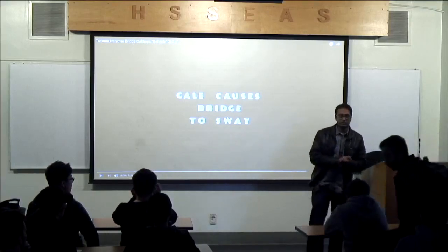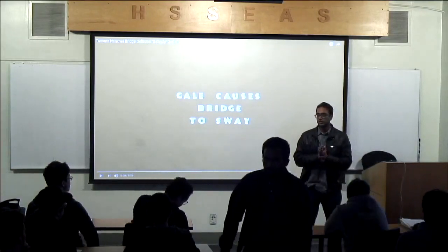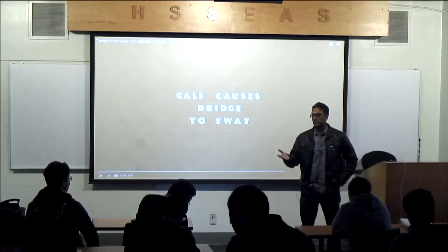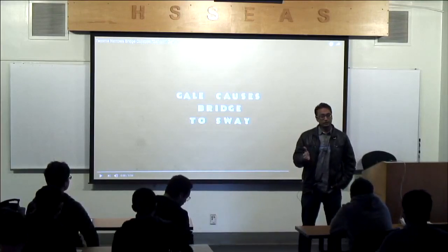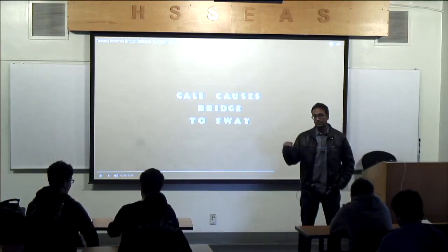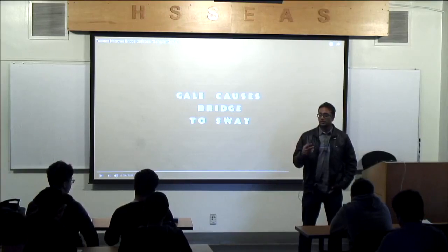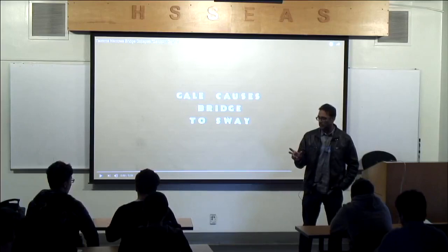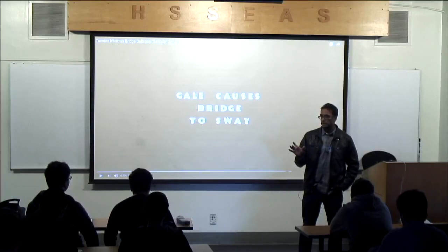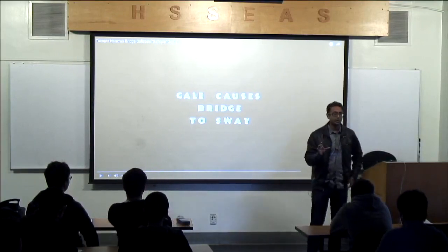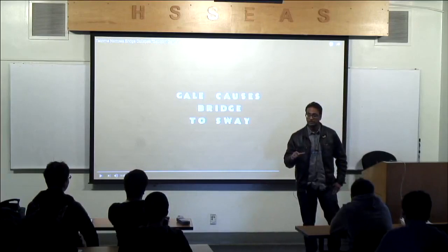Welcome again. So we'll be discussing transient solutions, transient analysis, where the solutions depend on time. That's really what we're discussing. In the previous lecture, what we learned is how to discretize the spatial domain using finite elements, and then we learned how to march the solution, find the solution as a function of time by discretizing the time domain using time integration. And I taught you a Newmark beta procedure in how to do that procedure.